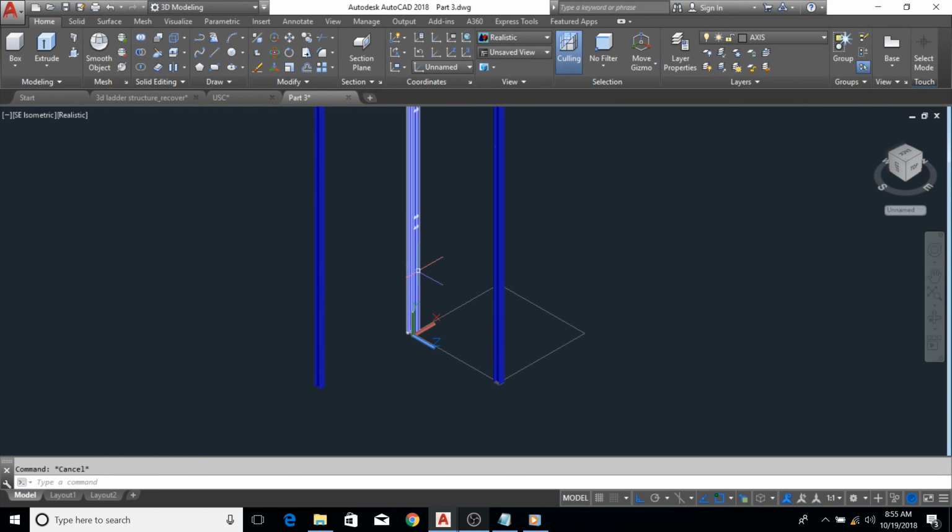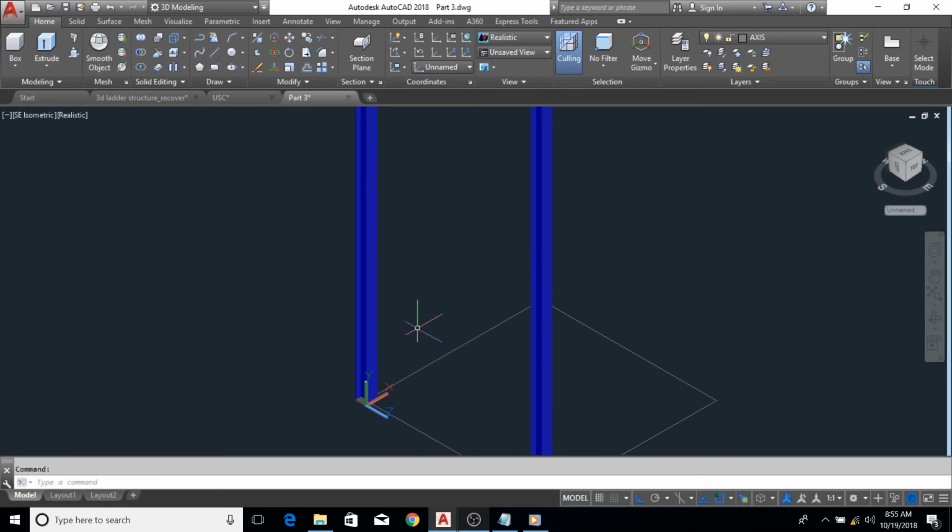So what I'm going to do is that I need a section. I'll draw a rectangle, D, enter. On the y-axis, the thickness of the flange of the column was 0.68, okay? Enter, by 15.2, enter, okay?